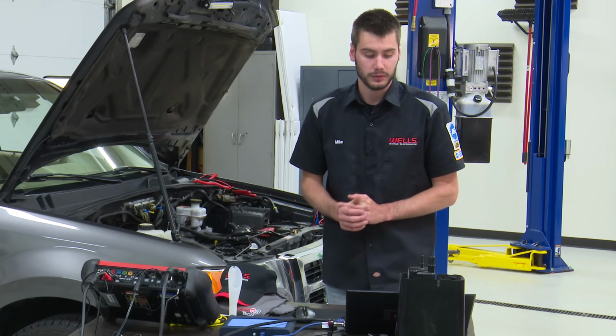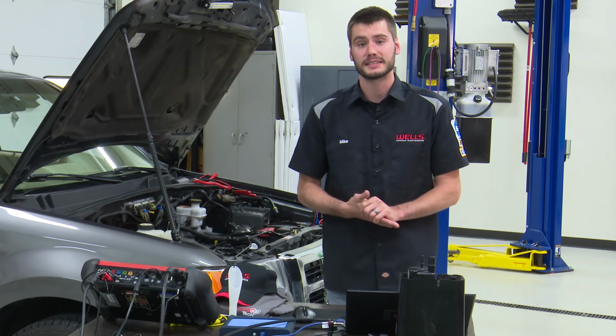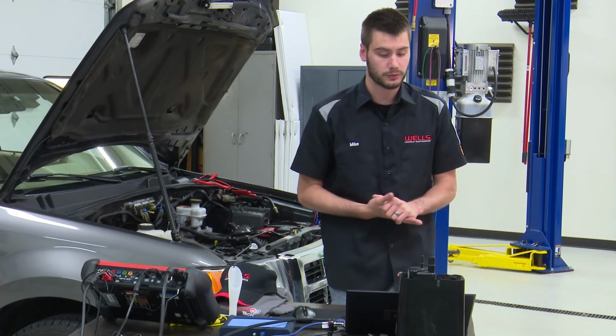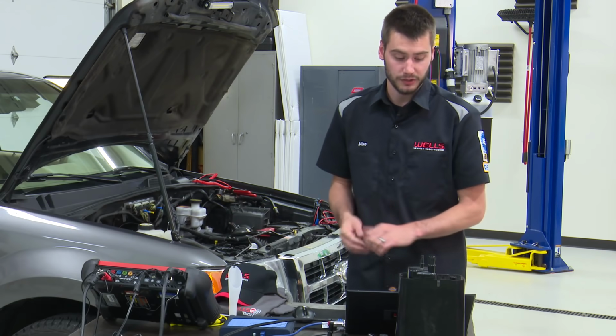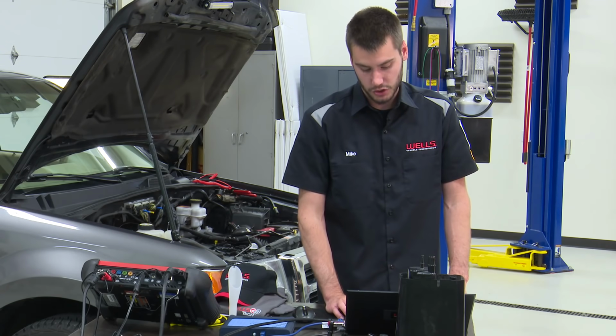And then we typically will have a check valve or float at the base of the filler neck that will seal off the filler neck to not allow any sort of liquid fuel to travel up that neck. And then we also have a larger, higher capacity charcoal canister.